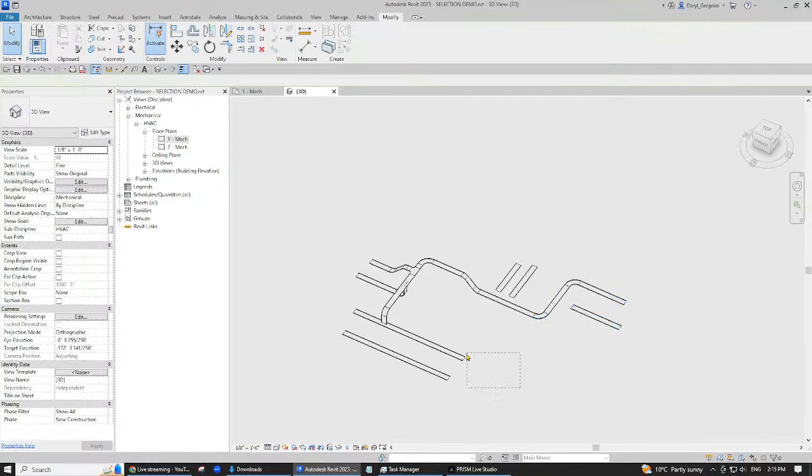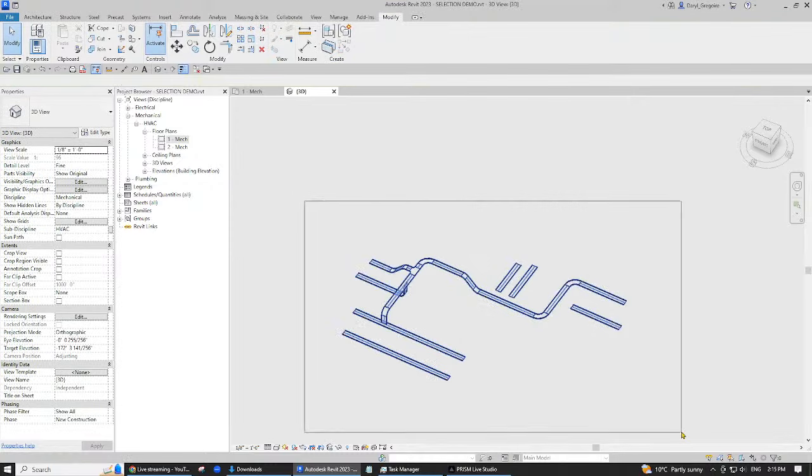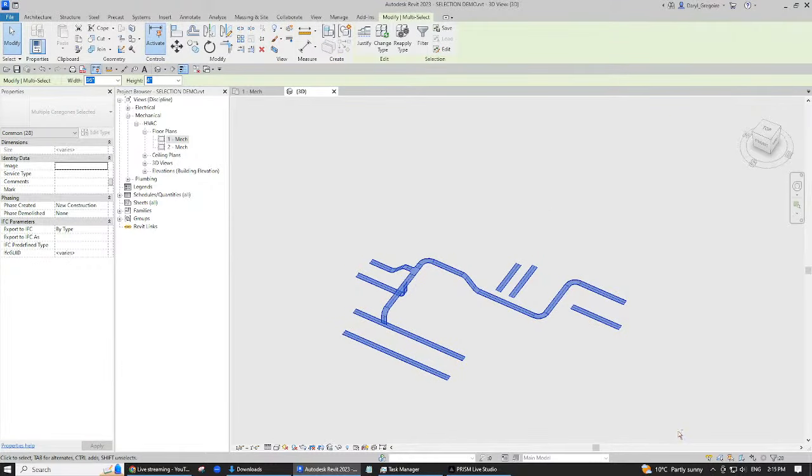Crossing to the left means it just has to touch it. That's all it has to do. So you could window all this, hold your shift key in, and do a crossing and remove that. So I'm removing objects with the crossing box. Then I can control add back with the crossing box, or add with the window box. So adding, removing with window or crossing.